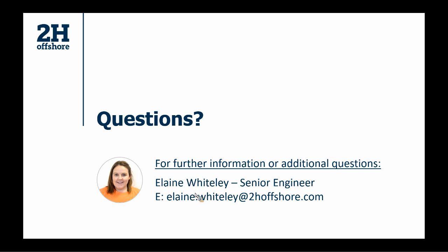Next question. How are the operators dealing with all this inspection, rework, or redesign, if needed, to keep the integrity, especially in the current oil and gas downturn? So actually, managing the conductor and staying on top of the integrity management, it's usually cost saving in the long run. So if the analysis has already been completed, if you're looking at changing the centralization, it's not like you're starting all the analysis from scratch. You're simply making a tweak to the model and rerunning existing analysis. So it's actually quite quick and it's quite cheap to do, to look at a revisit to a centralizer.